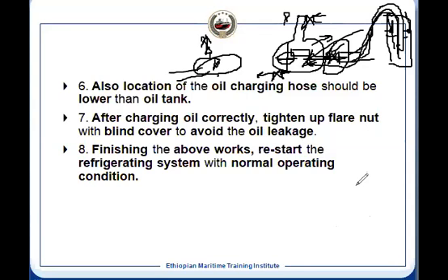Yeah, the compressor will stop early because of safety, because when it senses low pressure, it will stop early. So in that case, how do we make it zero? You have to bypass it. If any safety is interfering, because you are doing it manually, you are there, you can monitor the pressure, all the parameters you are monitoring when you are collecting the gas temporarily in the condenser. If required, you can bypass that. There is no problem of bypassing that at that moment.